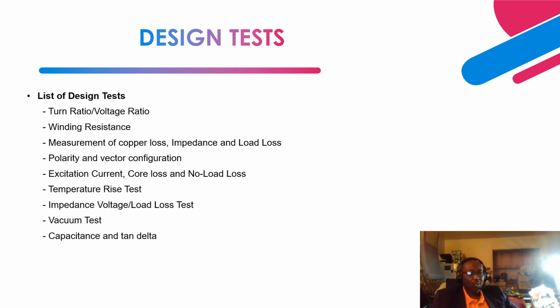Next, impedance voltage or load loss test. So that is similar to item 3, copper loss, impedance, and load loss test. Next is the vacuum test. Okay, so we perform this test to measure leaks on the power transformer.